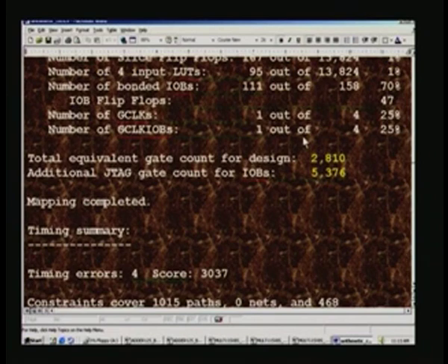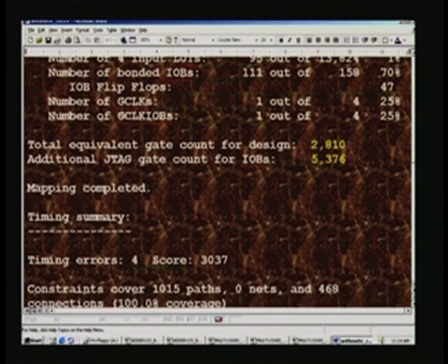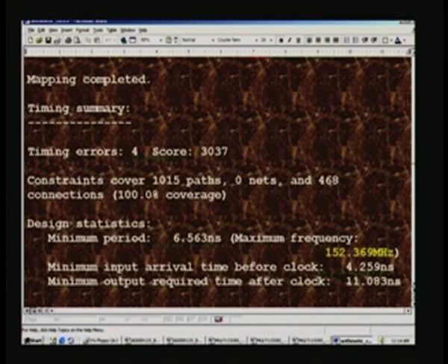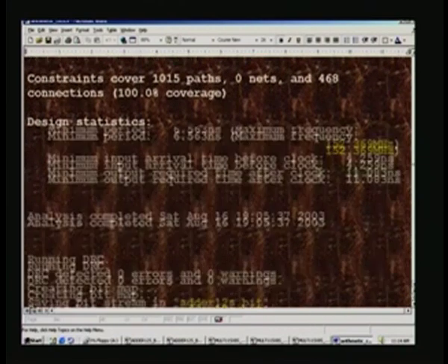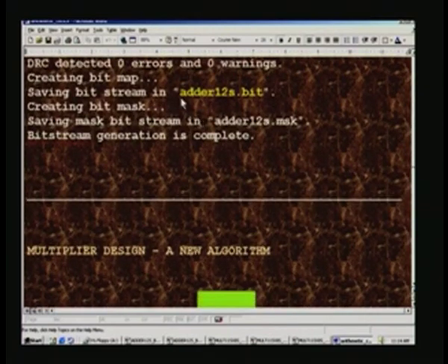And what is of interest is the number of gates, standardized to say 2-input NAND gates, and it comes to around 7,000-8,000 gates nearly for a single adder, which adds 8 numbers of 12-bit signed numbers. And now surprisingly Xilinx reports a much higher frequency here, say 152 megahertz, and also produces a dot bit output, bit stream output.